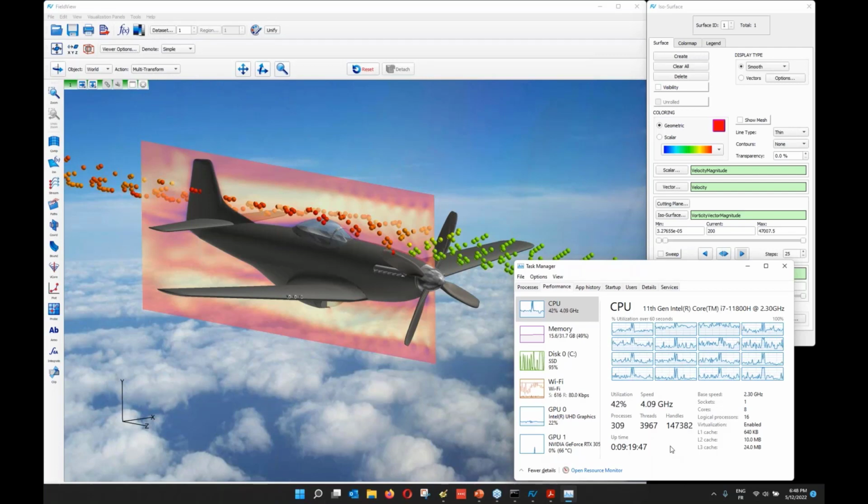So that's for parallel. For most of the solvers that do export to the FieldView heavy-UNS format, the partitions from the solver are preserved. Sometimes you have to be aware of how to do it. So if you have any doubt, please don't hesitate to come to our support team or ask Raja or myself for how to do that.